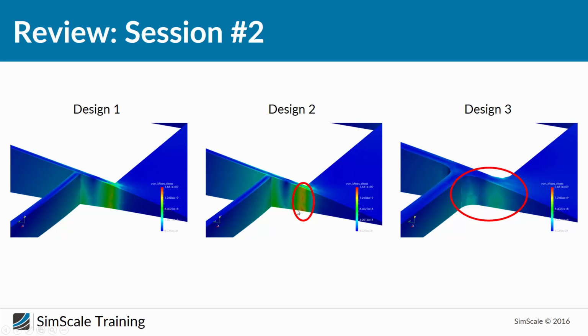And this is because the forces are now going another way through the material, and we have a lot of stress and force here, and this can really create a problem. By adding the fillets, we can solve this problem, because the cross section is not changing so fast. These sharp edges are really an invitation for stress, so this helps us to reduce the stress. These are two different things you should really keep in mind.